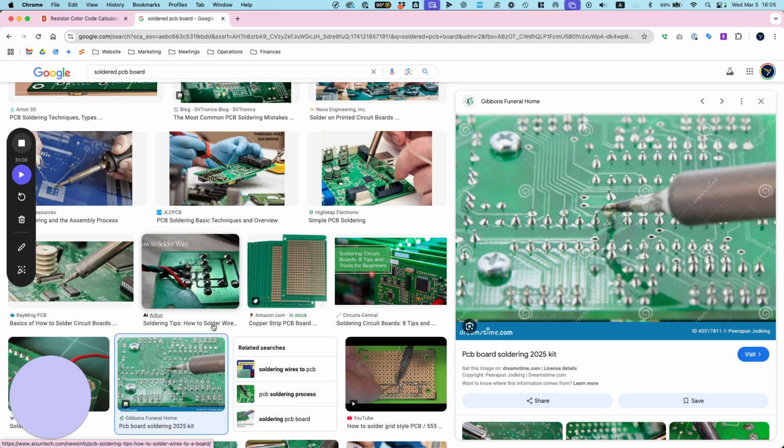But you can see here, we are able to determine the percentage from something that has no apparent meter on it, right? These have meters built in, these don't. There's no way to tell except for you to take a multimeter. Or you can plug into the drone and look through the goggles, which has a built-in multimeter, right? That's the way to tell what the voltage is. A lot of times, FPV, they're not going to tell you battery percentage. They're just going to tell you voltage.